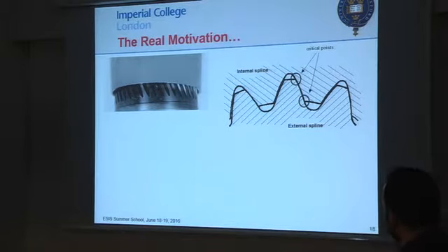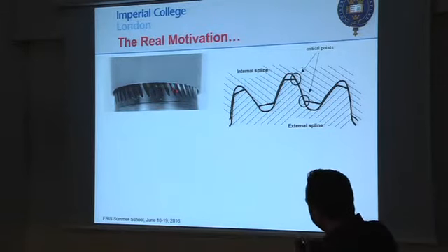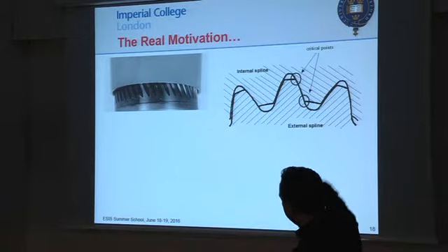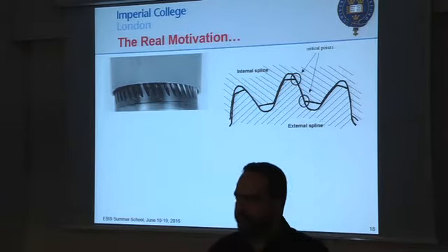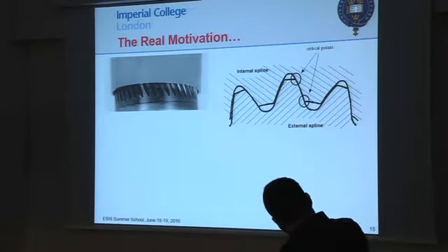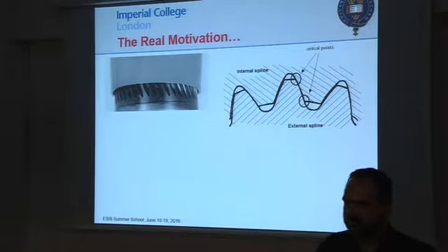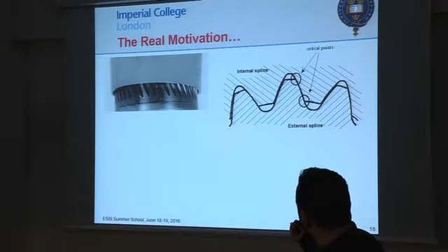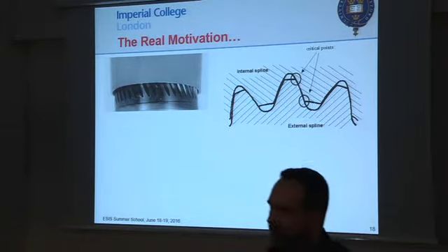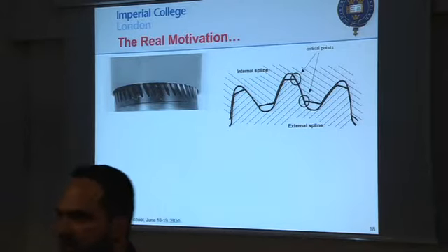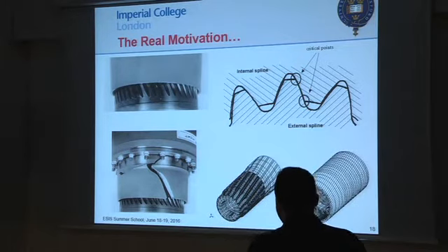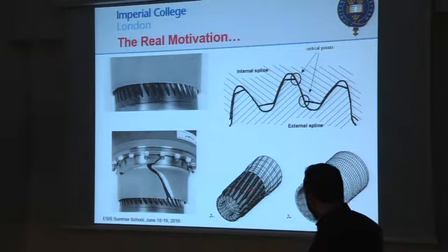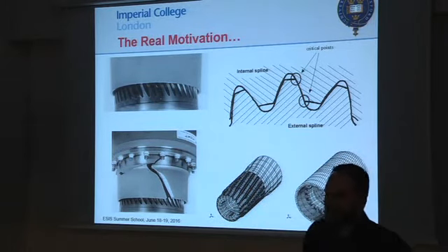You've got a spline shaft. In this case, as I said, I've got a male and a female shaft coming in, and they turn and transmit torque. They transmit torque by having contact between the teeth at those points. As you can see here, there's a sharp corner there, sharp corner there. Yes, they've got some tiny radii, but actually they're very sharp features. And the idea is these things crack, and these things sometimes have proper failures.